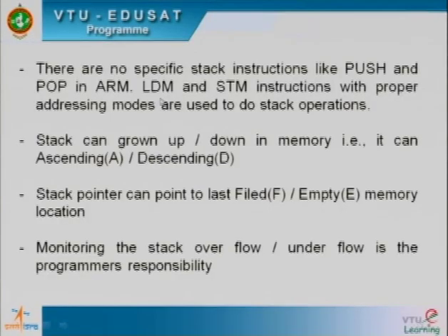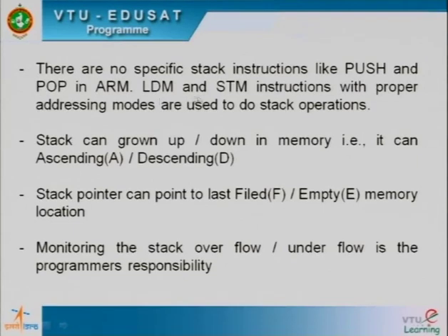But let's look at this instruction. LDM and STM instructions with the proper addressing modes are used to do the stack operations. So there are no separate instructions. LDM and STM themselves will do the stack operation with the proper addressing modes. What are these proper addressing modes? We'll look at that in the next slide.